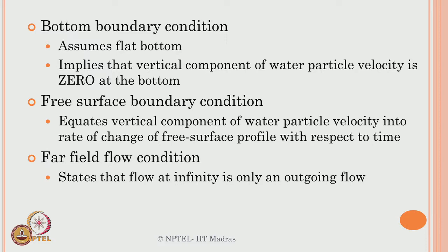Generally in analysis the bottom is assumed to remain flat. However, in the ocean bed, flatness is not ensured and roughness is also not ensured. So, however, we assume that the sea bottom remains flat, because the distance of the flatness of the surface from the edge of the cylinder is very large compared to the water depth of the seabed where the structure is installed. Therefore, the assumption is very much valid.